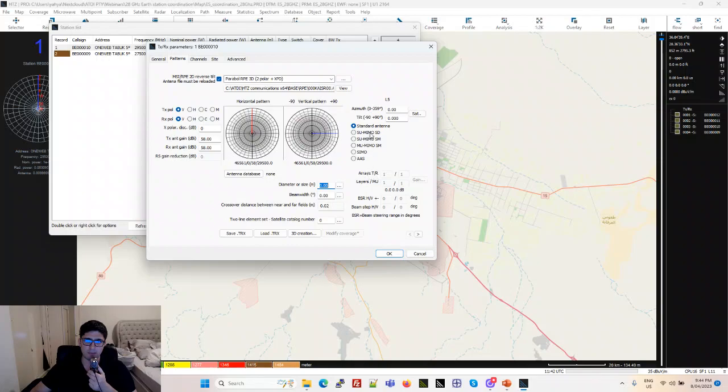I can emulate that by going with a smart antenna, and then I can start, for example, pointing up 10 degrees, and then swinging up and down by 5 degrees. Because it's a rotational antenna, you can rotate horizontally by 180 degrees. What does it mean? It means the horizontal antenna movement is 360, plus or minus 180, but the vertical movement is only from 5 degrees to 15 degrees, and you don't need to go higher, 20, 30. It doesn't make any impact in terms of emissions.